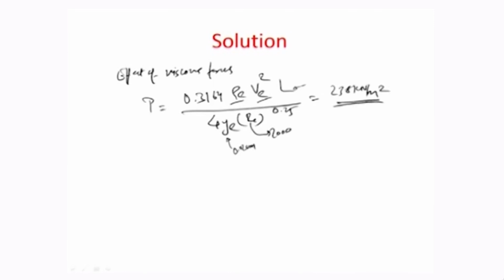So, it is a significant value, okay, and therefore, if you look at the area of the tool face, this area of the tool face is equal to 25.4 square millimeter, and on such a tool face, if such a large pressure of the electrolyte is imparted, the amount of force that the tool face would have is basically, at one side, when the electrolyte has just about entered, the L is 0, okay.